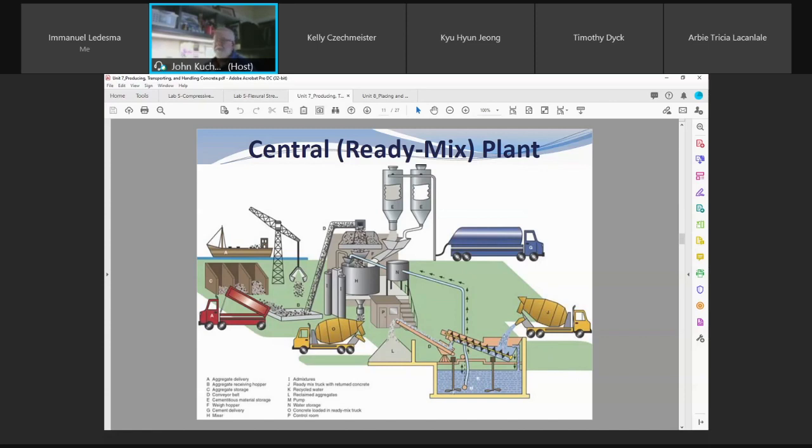They'll have a settling where a lot of the heavier aggregates will settle out, and they'll have water going up with cement and paste. Here you can see they're pulling out the fines that get washed out with the wash water, and they may reuse that back in, or use it for grade or base course. So you can see they're recycling their water.